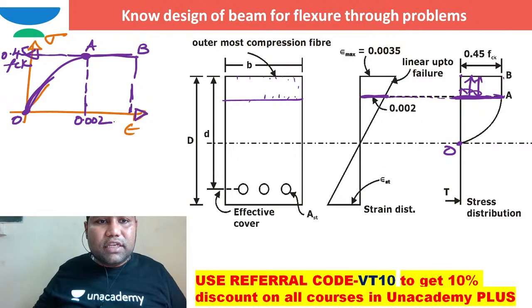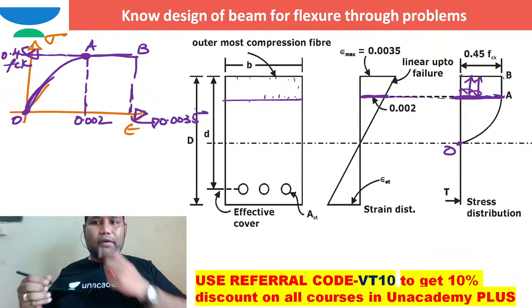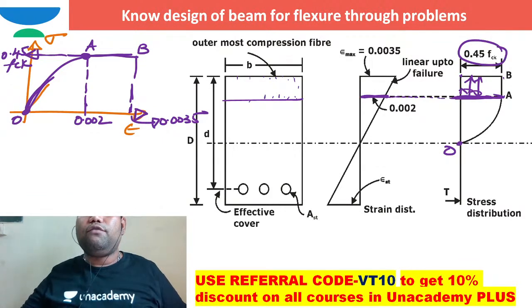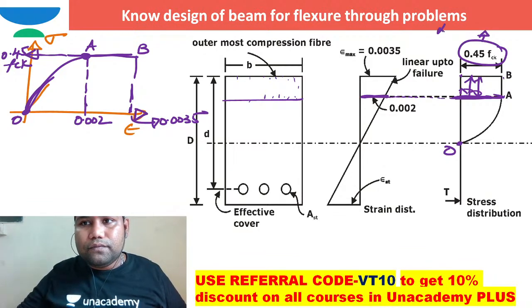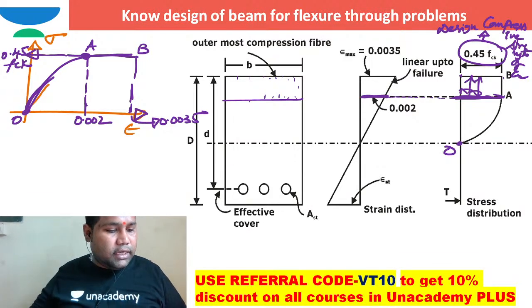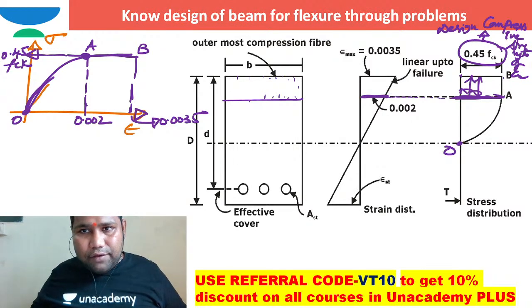So I can say this is 0.002, this is 0.0035. And you got why I got this answer of 0.45 FCK. This 0.45 FCK is the design compressive strength of concrete, right? So that's the reason why we got it as 0.45 FCK.